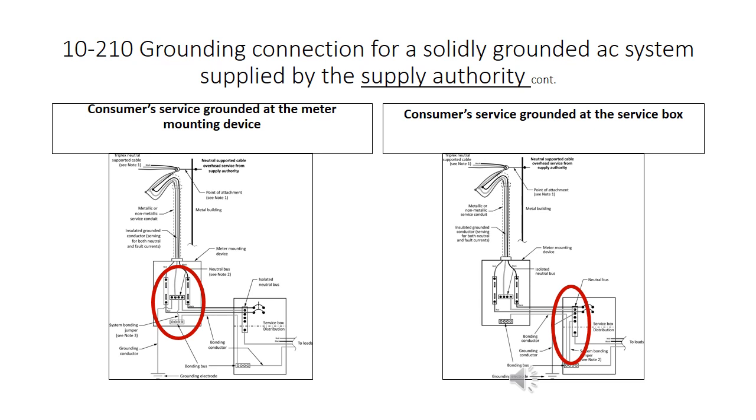The picture on the left, caution must be used. Presently, there is no CSA standard for grounding in a single meter base. Therefore, this method is currently not approved. If you require further information, please consult your local authority having jurisdiction and your local utility for additional information.